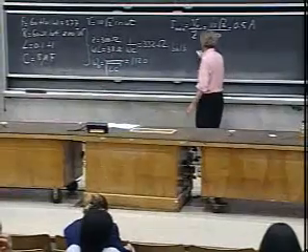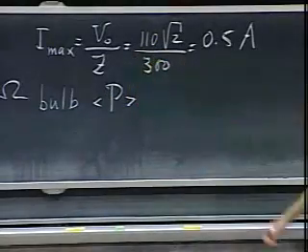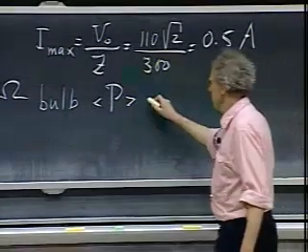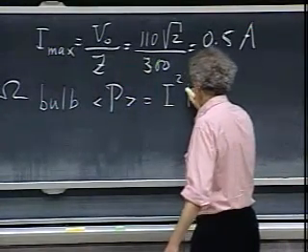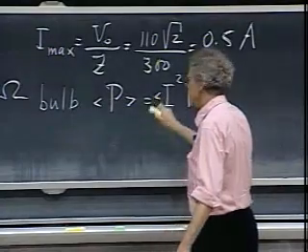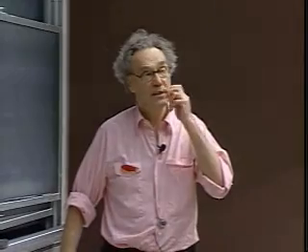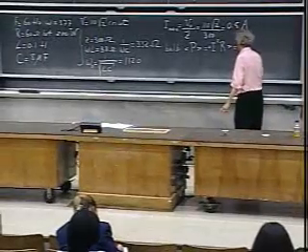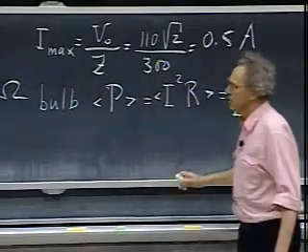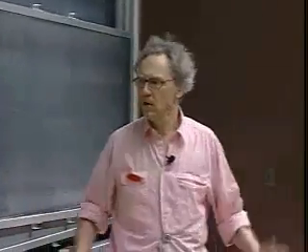The average power over one full cycle of my oscillations equals the mean value of I squared R, time averaged. The time average value of cosine omega t squared is always 1/2. So this 1/2 is the result of the fact that the I has a cosine omega t, and you square that, and you get 1/2 if you average it over oscillations.